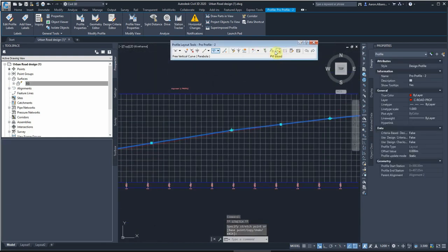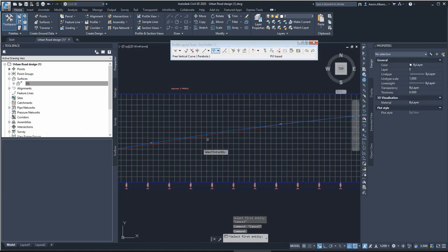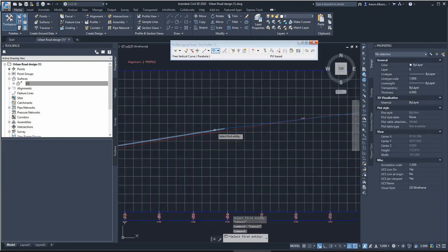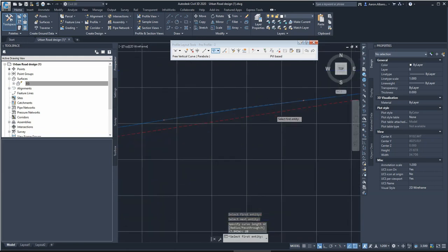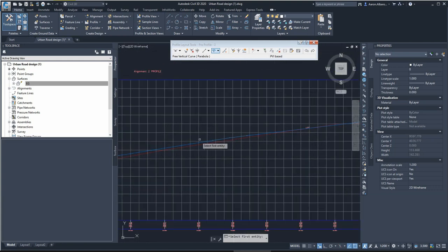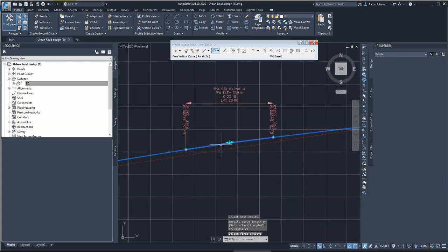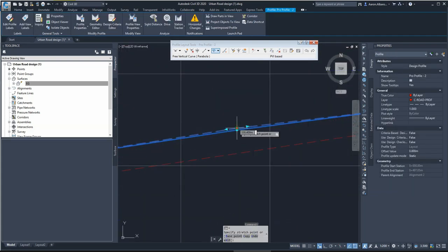So going back, adding a free curve. This is the first entity, and the second entity, and it asks me what the K value is. I'll choose 20, although we will have larger than that. Enter, and that's created the curve here. If I finish, I can continue with the other point, but just so I can show you, by clicking enter, that will finish that. Okay, and I can move it down now the way it was.